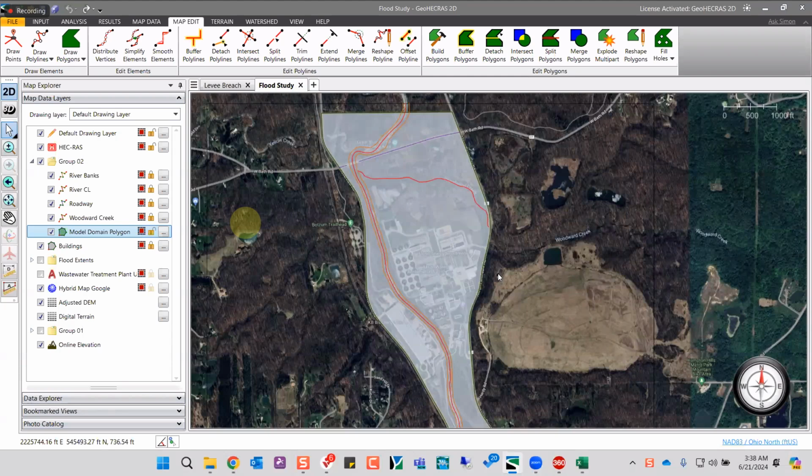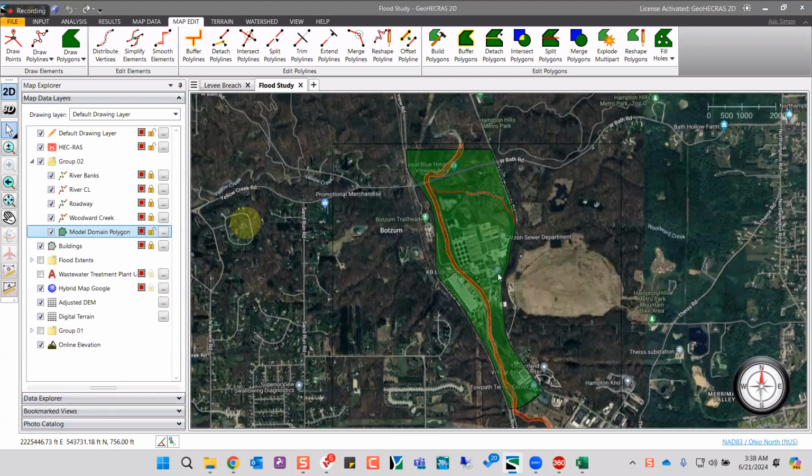Now, 2D models are really simple, very precise, and you can create these 2D models easily. Once you're thorough with your project objective, and once you have the necessary data requirements for the model, whenever you can, go ahead with the 2D model. And do not unnecessarily complicate it with hybrid models. Hybrid models are not always the right solution. Prefer to do it either in 1D or in 2D. If you can create a 2D model for your project, go ahead and create your 2D model only.